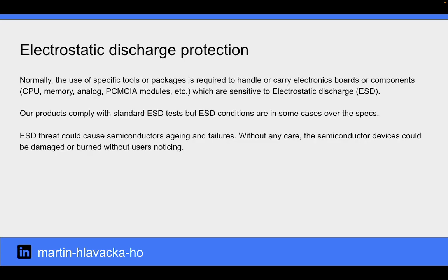Electrostatic discharge protection. Normally, the use of specific tools or packages is required to handle or carry electronic boards or components that are sensitive to electrostatic discharge. Our products comply with standards ESD test, but ESD conditions are in some cases over the specs. ESD threat could cause semiconductor aging and failures. Without any care, the semiconductor devices could be damaged or burned without users noticing.